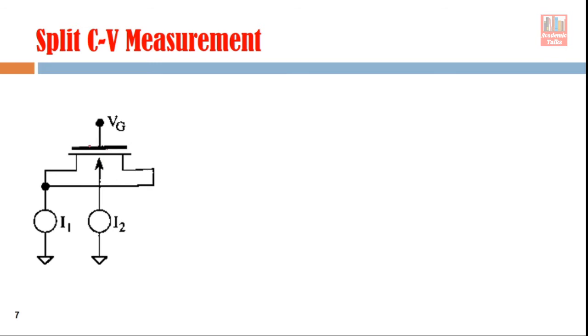So one terminal is the gate terminal, and the second terminal is the channel or bulk terminal, right? You have seen in the earlier slide that when the gate and source are connected together and a suitable gate voltage is applied here, then the channel has a single conductivity and acts as one electrode, right? And that way it is possible to find out the channel capacitance. So the equation for that is given here. I1 is the current which flows between the drain-source electrode and the gate electrode.